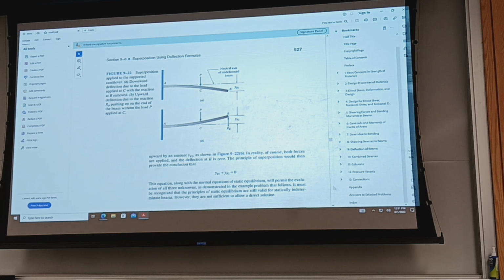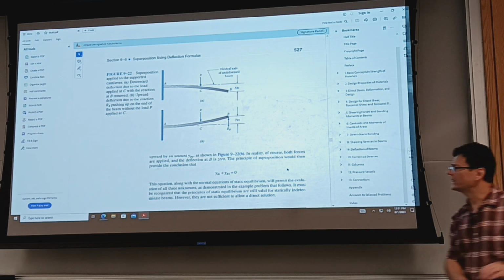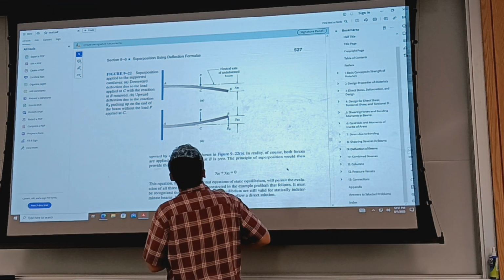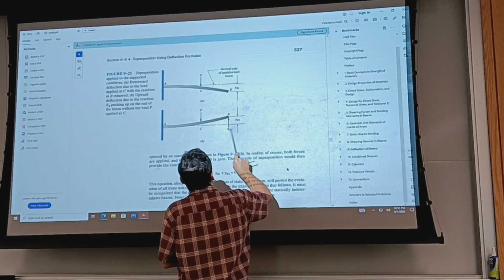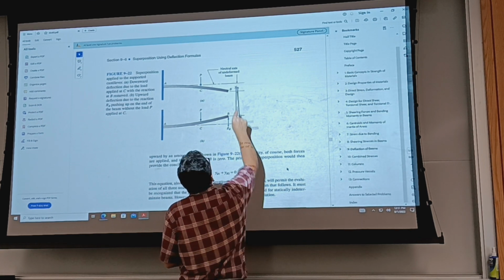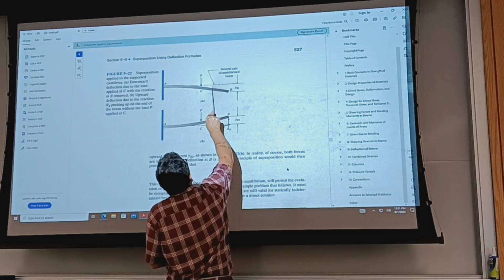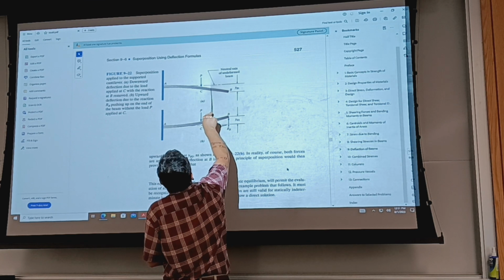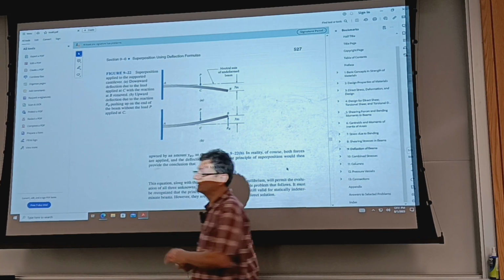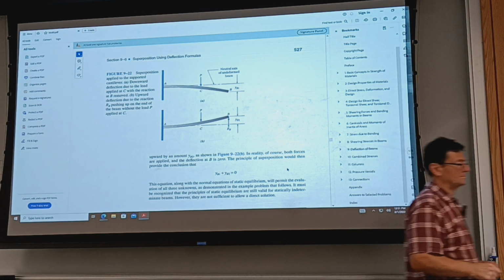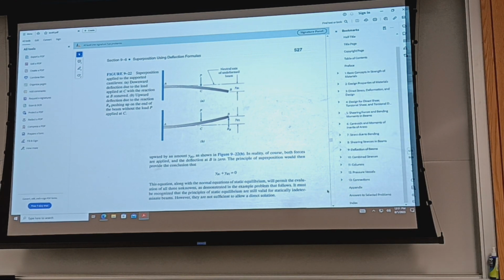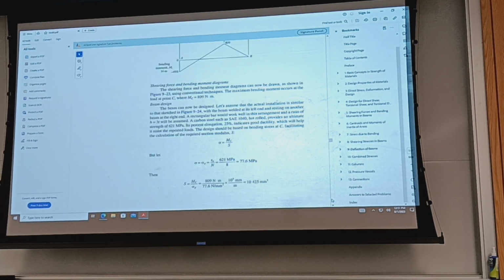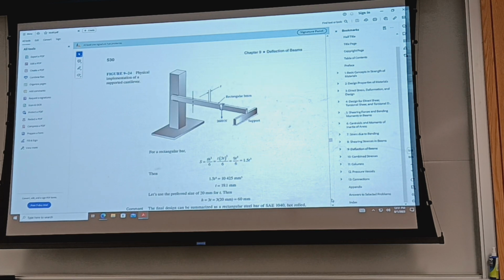That's enough for you to now calculate the shear force and bending moment diagram. Deflection elsewhere is going to be, once you figure out RB and this becomes equal to this one, deflection elsewhere will be, so for example, at the location that is 2/3 from A, just add this deflection to this deflection, with their signs, and the sum would be the net deflection at that point. Okay.